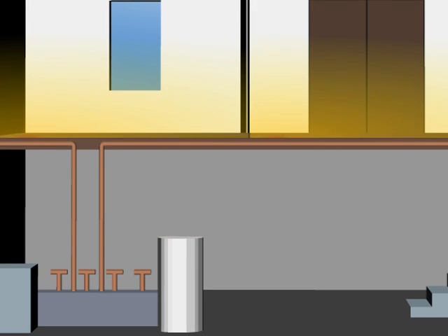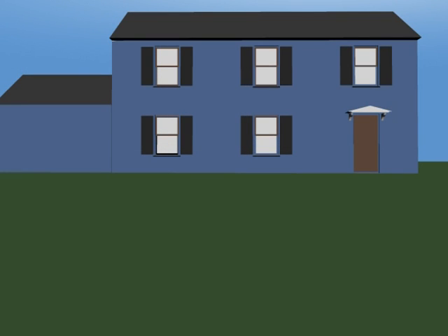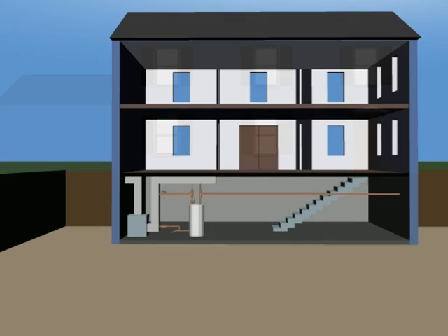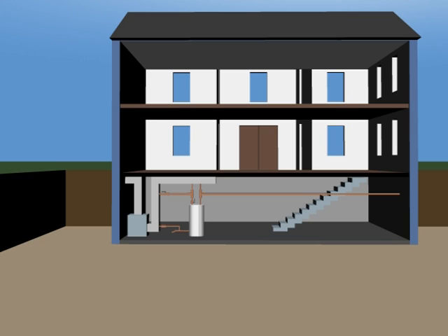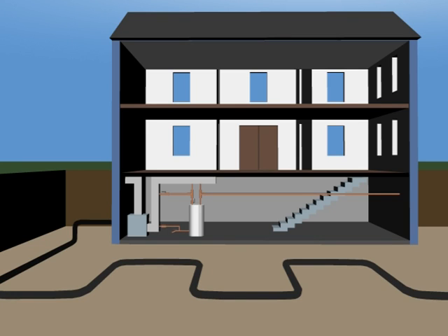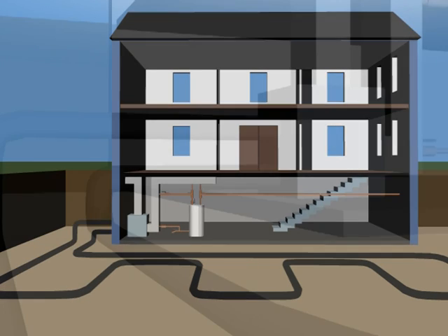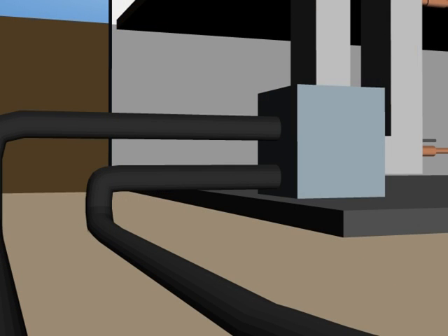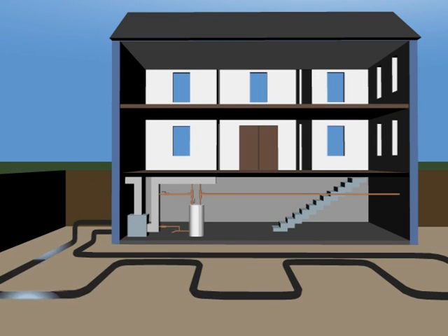The two types of heat exchangers commonly used are open loop and closed loop. A closed loop uses a system of continuous underground pipe loops in which both ends of the pipe system are connected to the heat pump, thereby forming a sealed closed loop. Water, or a mixture of water and environmentally friendly antifreeze, circulates through the loop to transfer heat between the heat pump and the earth or return heat back to the earth.